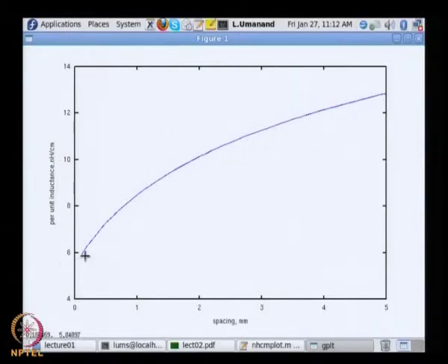Okay. See that with the spacing the inductance value is increasing. So, if you space the tracks more and more wide, you are creating a larger and larger loop area, and this larger loop area results in more inductance, and this has more mutual inductance capability, which can link to other circuits. Okay. So, that is one important point that you should remember.